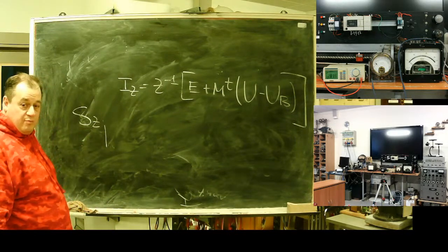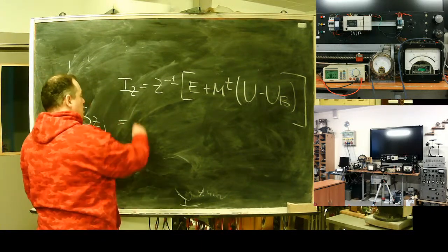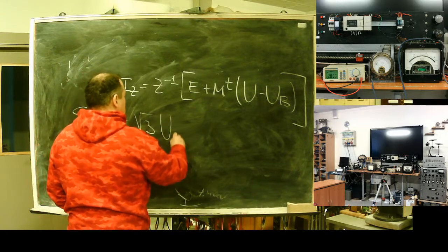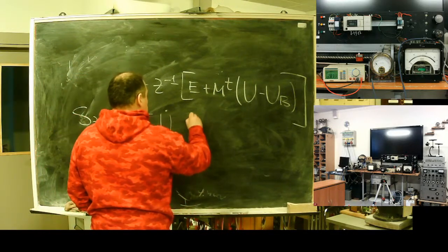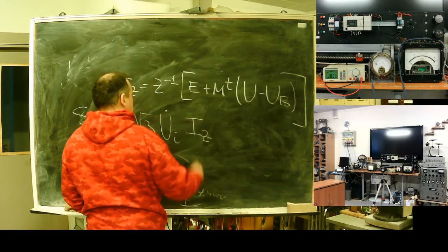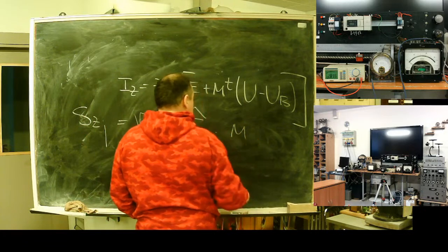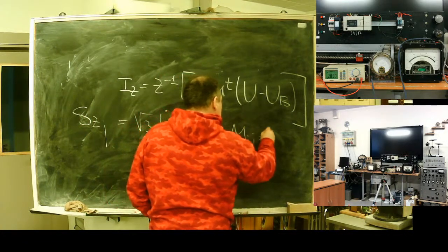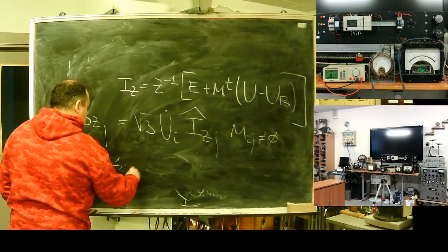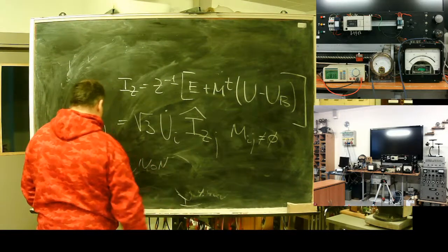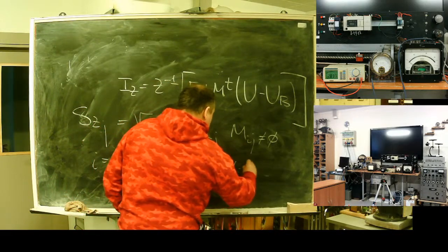Power flow in the branch number k equals square root from 3 times nodal voltage at node I multiplied by branch current conjugated, where the incidence element is not 0, for I from 1 to number of nodes and k from 1 to number of branches.